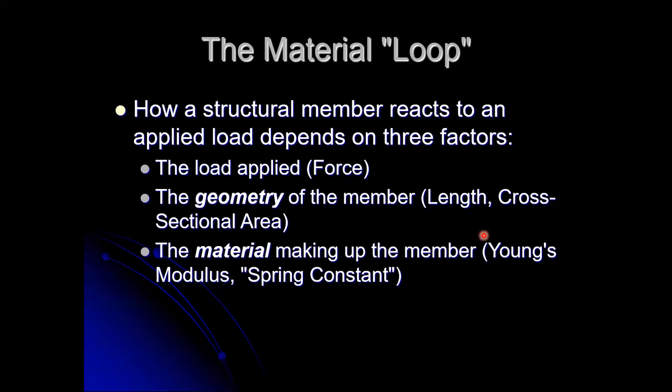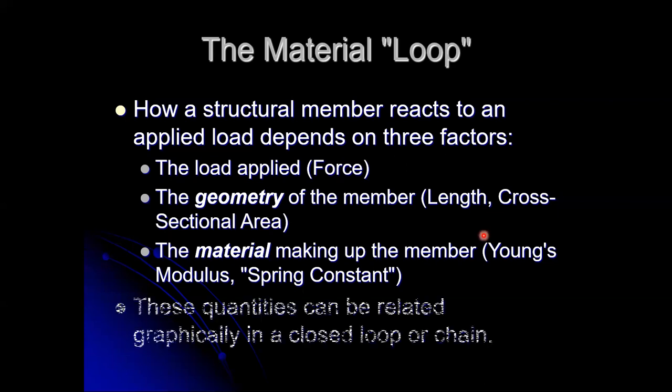So all these materials have different properties, and they enter the whole setup through these constants, through Young's modulus and through the spring constant. We can put all these together and relate them in this loop or this chain, and it's essentially describing how the material ends up responding. From the outside picture, we're interested in length change. I want to know, if I load this member up, is it going to stretch out too much? How much is it going to stretch out? That's the response to the load.